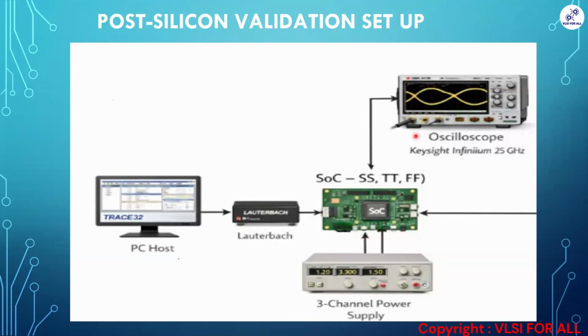To analyze that logic, we'll use the logic analyzer. Prodigy is also one type of logic analyzer. We'll be setting it as master mode or slave mode, and we'll capture and display the digital signals.